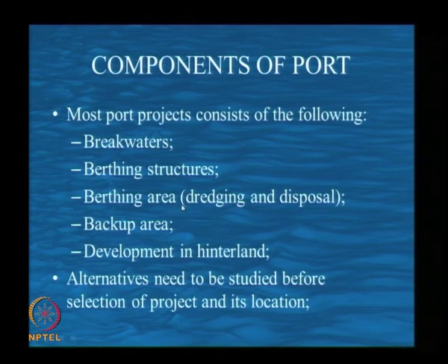Then berthing area, we have to do the dredging and disposal. The berthing structure is on the land side, the berthing area is on the harbour side. Then how to develop the backup area, then development in hinterland, that is road, rail and pipeline or inland water transport connectivity. So, we have to study various alternatives before selection of the project and its location. This is what is to be done.